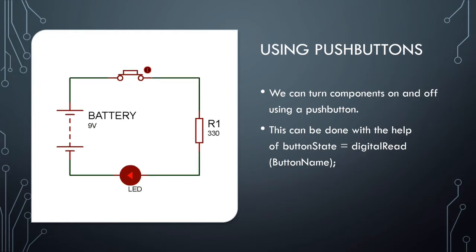It is working, great. So you can see that when the button is making contact, it's actually closing the circuit and allowing the LED or whatever component is at the bottom to turn on. And of course, when the push button is up, when it's not being depressed, the circuit has a gap in it. Right here is a gap. And so if there's a gap in the circuit, then the current can't flow and nothing will happen. So by pressing that push button, you are completing that gap and allowing whatever component is connected to it to turn on.